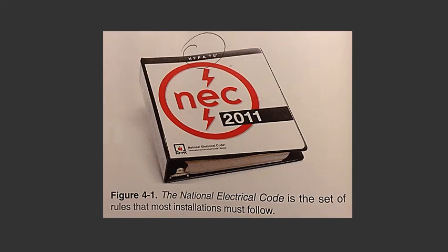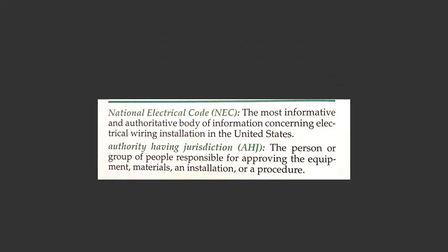Code enforcement. Almost every state, region, or locality has some sort of electrical code. Many use the NEC in whole or part. Article 90.4 of the NEC grants full power to the local inspection authority to interpret and modify meanings and intentions of the NEC. Further, some communities add regulations beyond those outlined in the NEC. For these reasons, the local inspector should be consulted for a copy of the local codes. Failure to do so will probably result in violations and inspection failures.